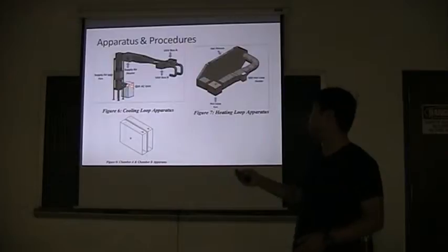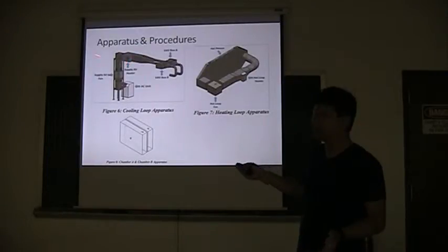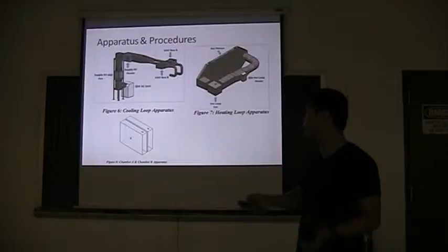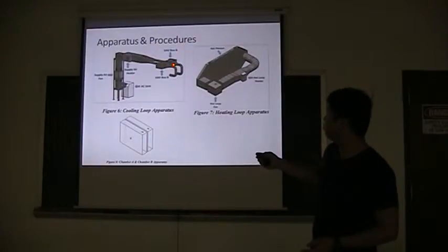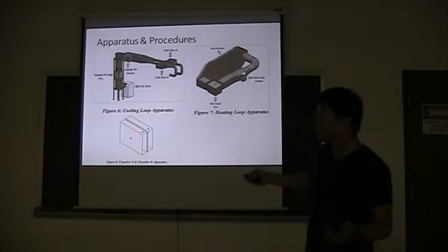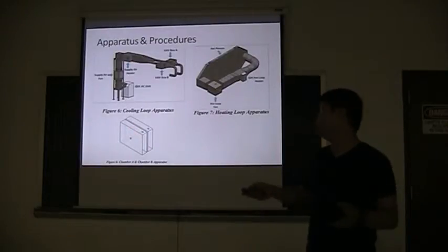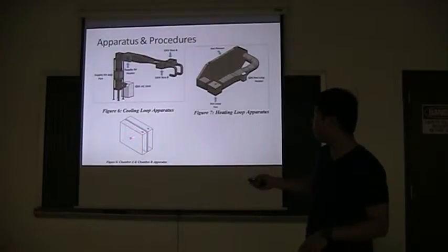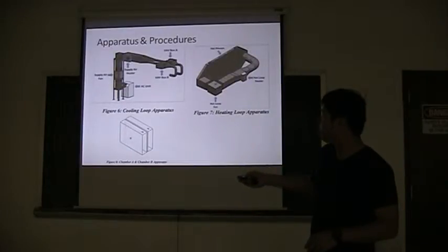It's a cooling loop, which has the AC, and it draws in the air, cools it, and goes to the supply air heater, which is just for our experiments, to heat up the air to a certain degree that we want. And it goes down here where there will be 2 boxes, chamber A and chamber B. They act as rooms. The only difference between chamber A and B is where it sits.